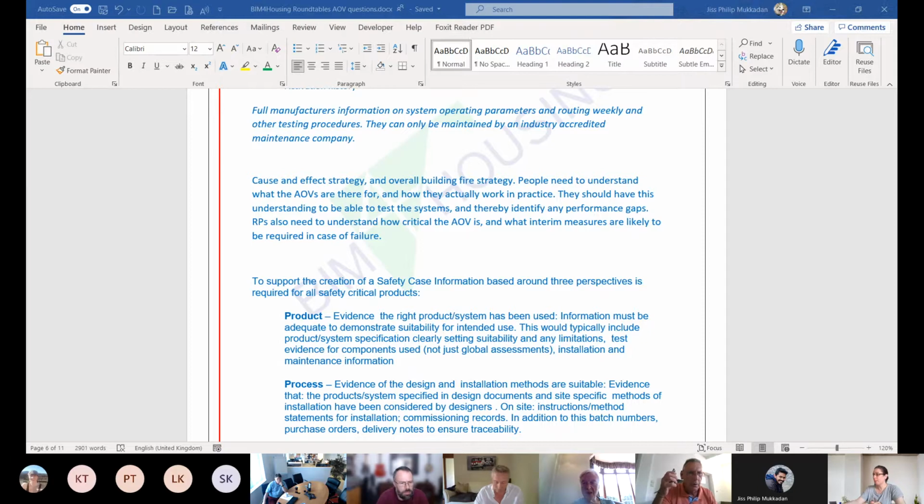Edward? Just one thought. It's on the 1.5 square meters. I think we need to be clear that's geometric area, clear area. And if you're having a proper system designed, you might have aerodynamic free area. Maybe you need to distinguish between the two in there, because if you do have a proper system, that might be something you want to know.